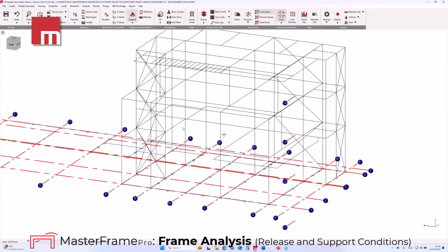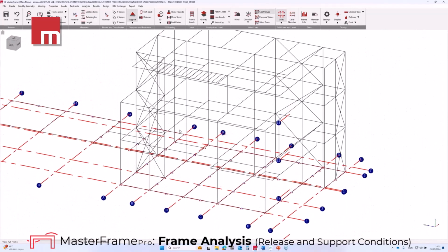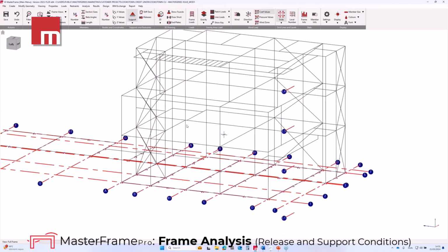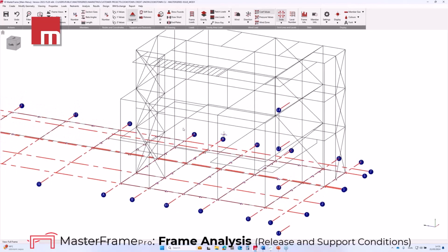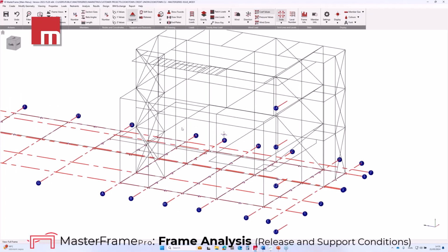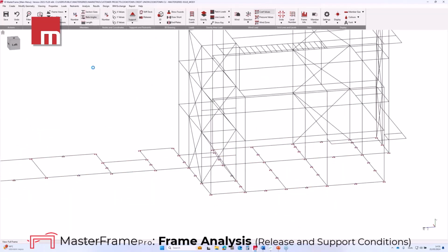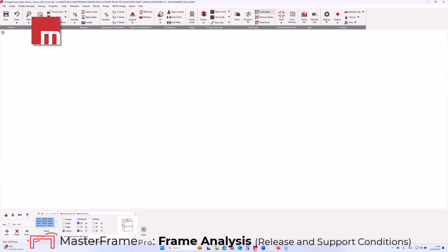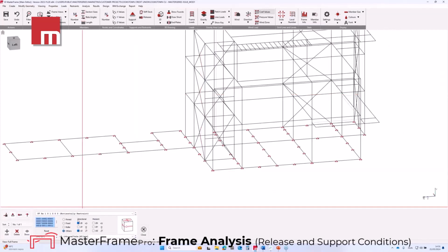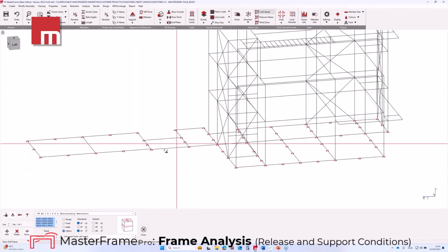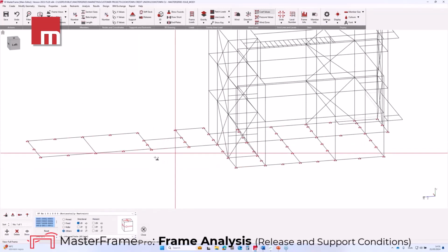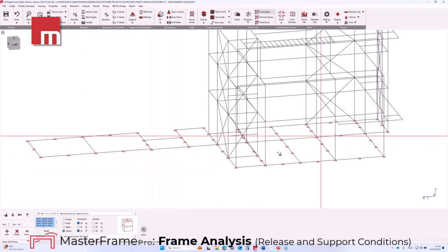As Patrick already mentioned, the ground beams are supported by steel piles. The support effect of the piles has been mimicked with two types of point support. In the horizontal X and Z directions, the engineer used static support at each position where there are piles. These static supports prevent any horizontal movement.